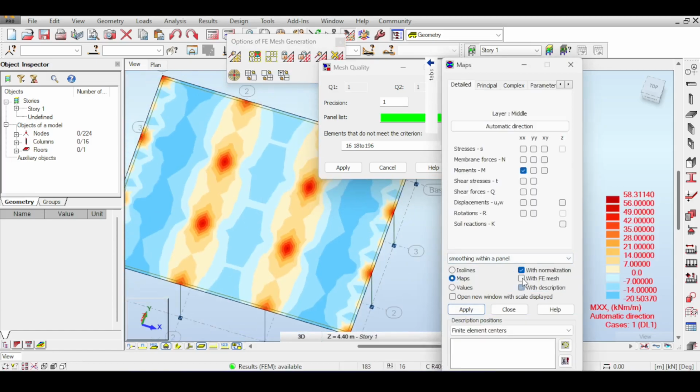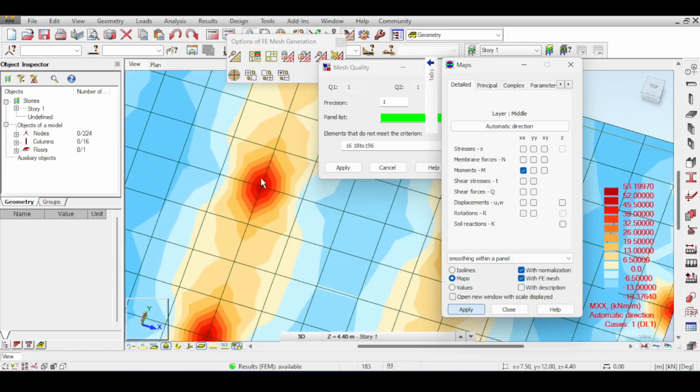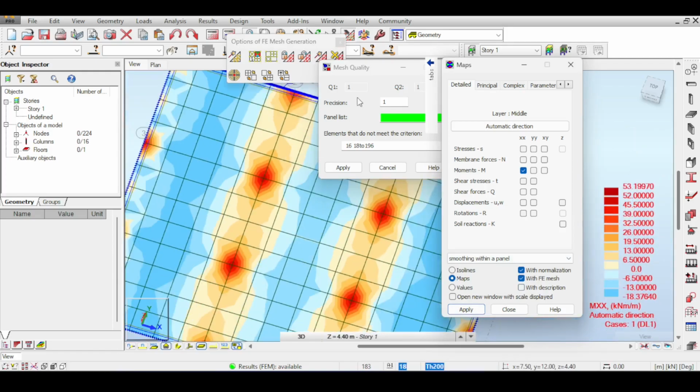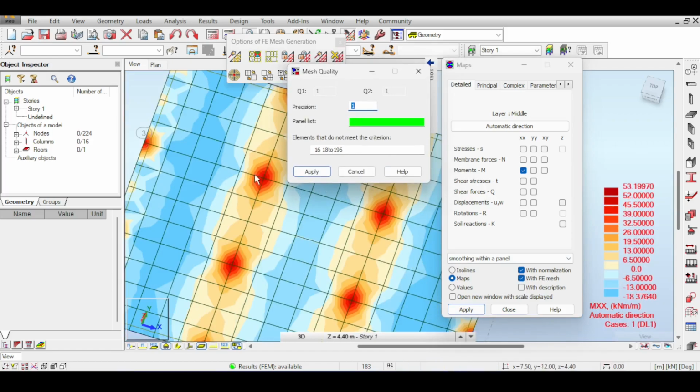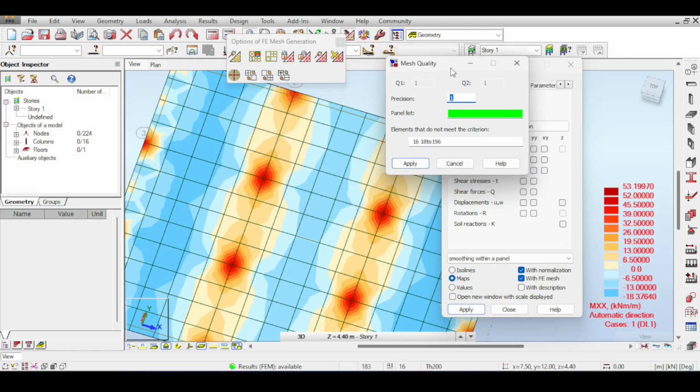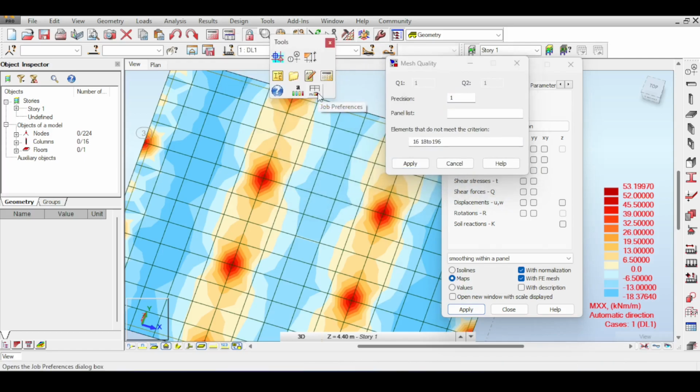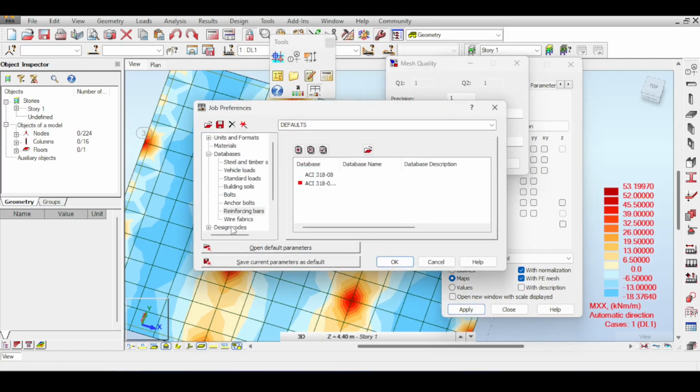You see, above the columns, you have rapid changes in both shear and moment. Those are hotspots, and your mesh quality should be good at those hotspots. And sometimes even your mesh fineness might increase or decrease. I never talked about this, I know, but now it's time.